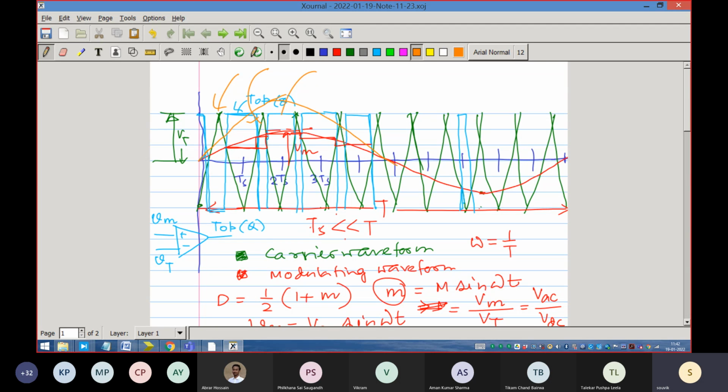So that is not allowed, and we must choose our DC voltage accordingly. We cannot afford to choose a very low value of DC voltage. That is what I am trying to emphasize here, because then it will go into overmodulation. This is called overmodulation. The machine has entered the overmodulation zone.